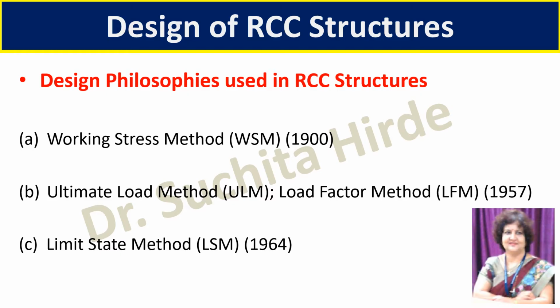Now in our IS code, this limit state method was accepted in 1964, but this method was not made compulsory in earlier codes. Now in IS 456-2000, limit state method is made mandatory. Now it is compulsory to use limit state method only.